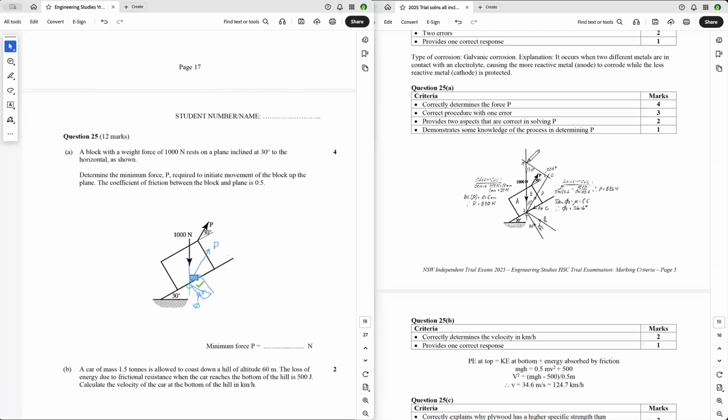So you start with the known force. I always use Bow's notation. So here we have A there, then we've got B, and then around here we've got C. And so you start with the known force, so you draw that 100 millimeters long or 50, what I've got here, and then you call that force AB, so little a, little b.